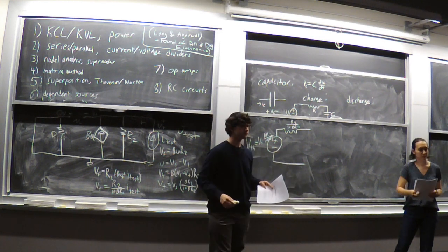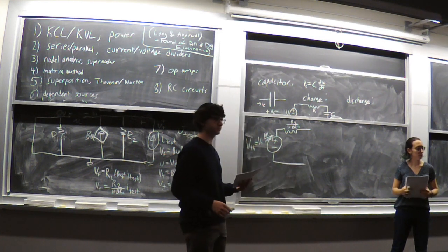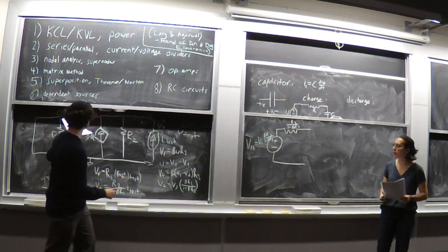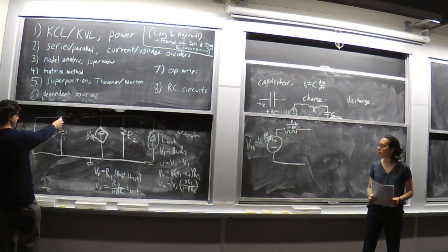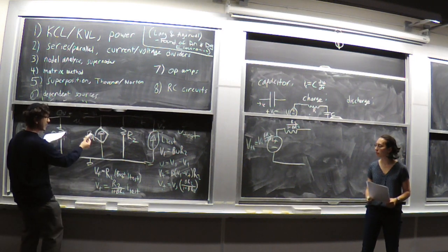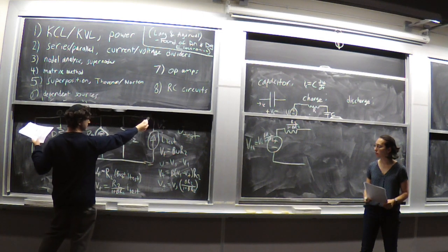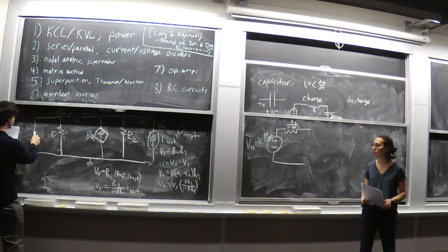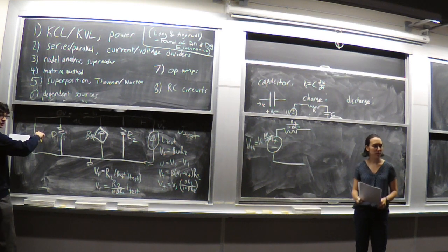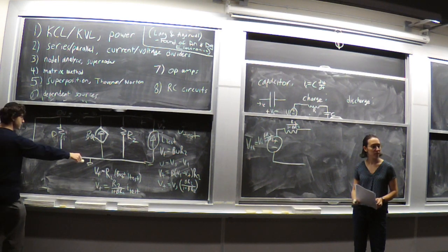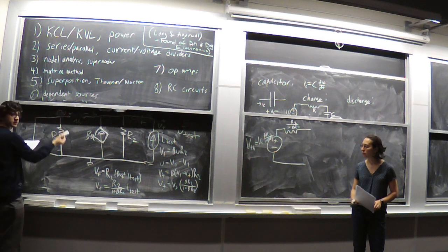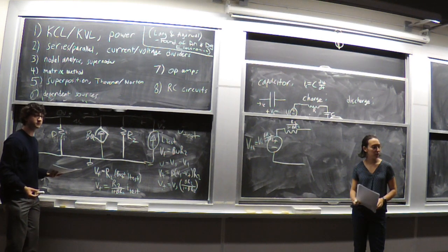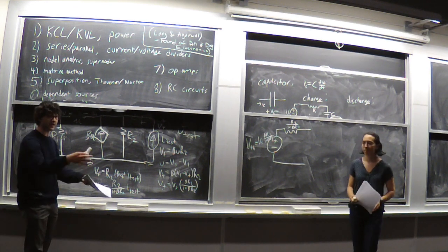Sorry, how did you get the voltage at U minus again? Yeah, sorry, I'm kind of rushing through it this time. It's the same trick as last time, where we look at what voltage is here and what voltage is here. V test is still the same node all the way over here. But now on this left-hand side, because we killed this independent voltage source and just made it a short circuit, a wire, the ground node extends all the way around and we have 0 up there. Okay, so before it was VS minus V test, and now it's just negative V test. Exactly, because VS turned to 0.